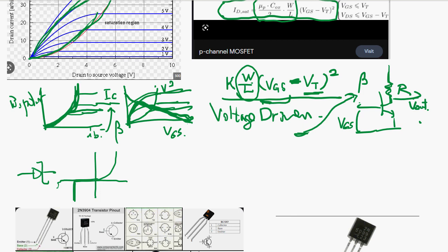So in a Zener diode, by increasing impurity in the silicon, there is a certain Zener voltage, and this is not destructive. When it reaches the Zener voltage, the current starts flowing in a very large amount. So the voltage is fixed, and how much current flows is pretty much determined by the outside circuit. Okay, so this is a Zener diode.